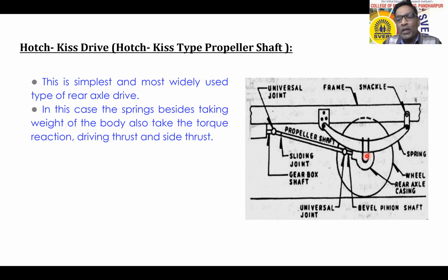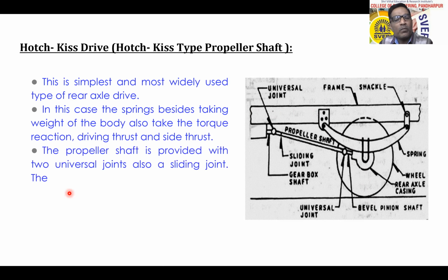That means when the axle is rotating, traction is available, the tractive effort is available here, and that tractive effort via this section will be given to this bracket, and again that is given through this long member of the chassis to the front wheel, so that the vehicle will propel in the forward direction.